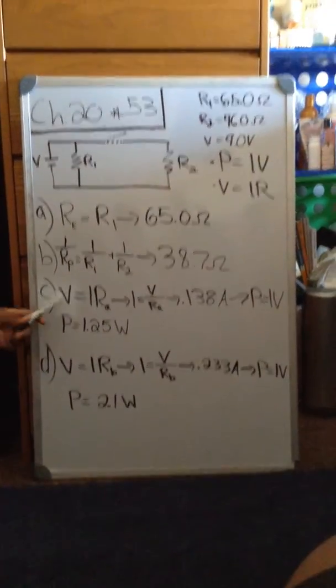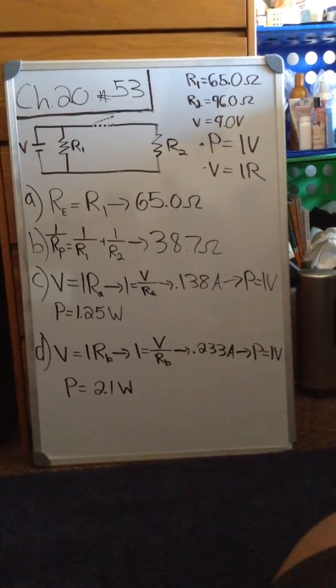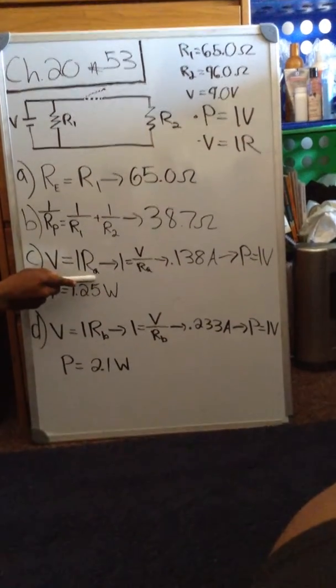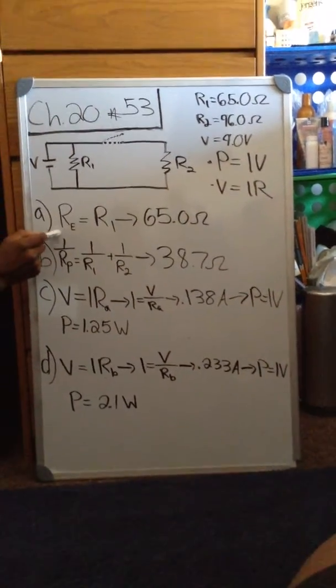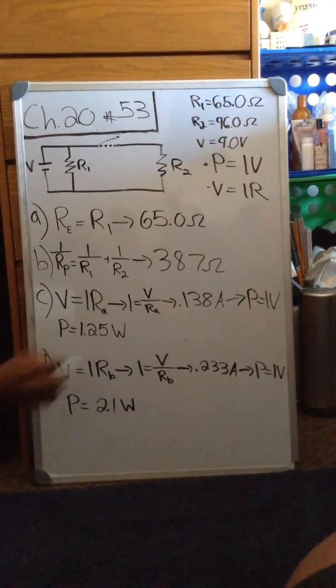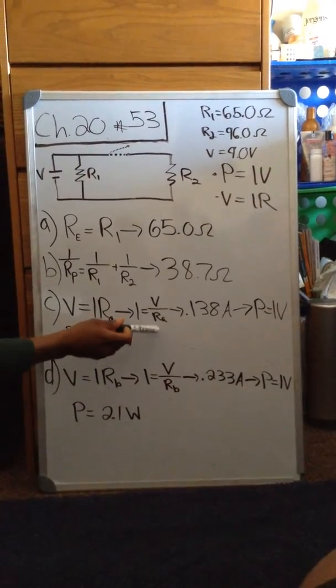So we use Ohm's law, which states the voltage equals current times resistance. So for part A, we see here that we have our resistance R_A, to reference part A in the problem, times the current would give us a voltage. Since we're solving for our current, we can manipulate this equation, so it's voltage over our resistance.